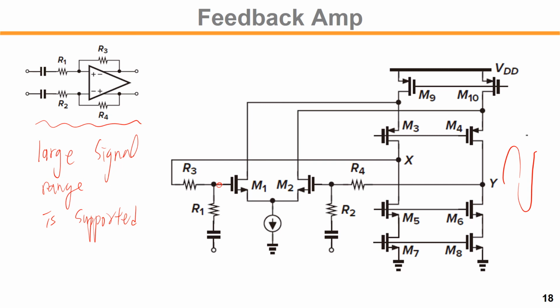But for the output common mode, we would like to maximize the output swing, so we would get the half VDD as the output common mode. Right? We have an up and down differential signal. The half VDD might be the optimum output common mode. And for this circuitry, because the feedback resistor had the 0 voltage drop because no DC current flows through, right?